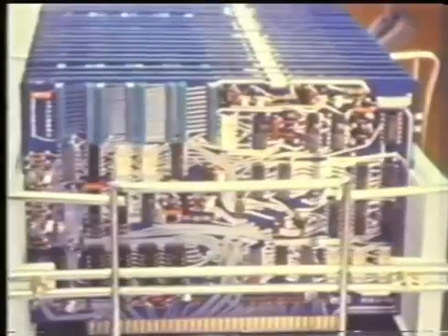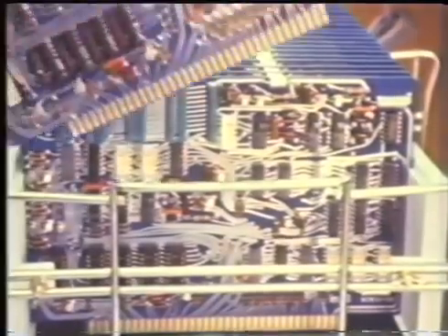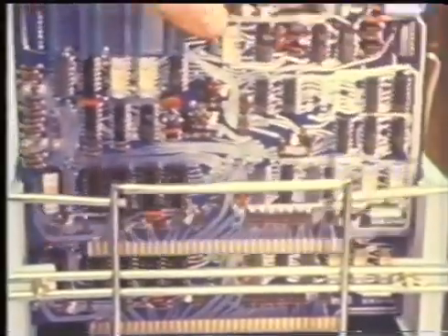The powerful instruction set for the MCS4 consists of 45 instructions, providing the logic functions which replace the old method of hardwired gates, flip-flops, and other logic elements. There are 16 instructions to perform data manipulating functions such as jump, increment, fetch, add, and subtract. 14 accumulator group instructions allow manipulation of the accumulator and carry flip-flop of the CPU.